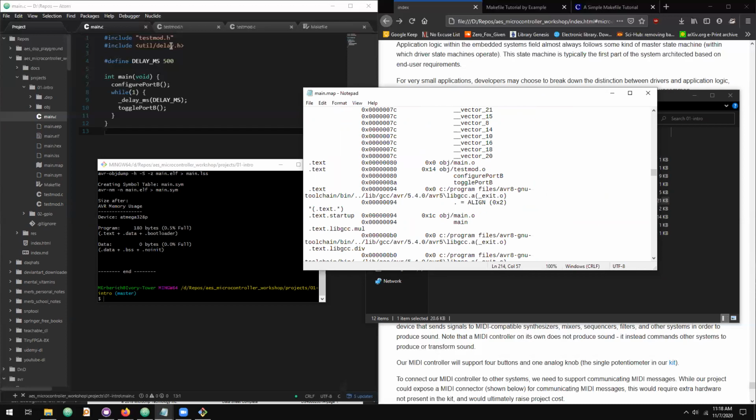So the map file is really useful for determining if a variable has been defined successfully, and if so, what its address should be. So if you're debugging, like, why are my pointers not successfully setting a variable, you can make sure that your pointer contains the correct address for that variable, or if you're doing function pointers, that your function is at the address that you're expecting.